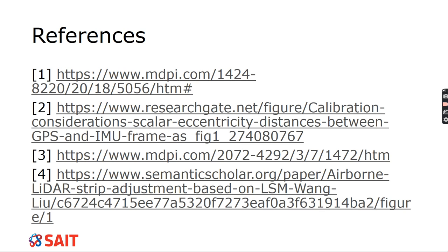So today's class was all about registration and calibration, talking about the geometry. What is the primary thing that we are trying to identify in LiDAR? We know that the LiDAR observation equation is what ties everything together in terms of getting our information to an Earth-fixed system rather than just the scanner itself. That's really complicated, and because of the complexity, we have a big systematic model that we have to use to try to reduce our errors.